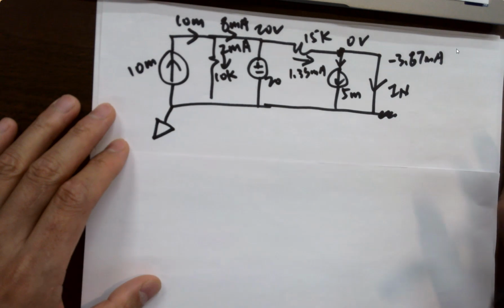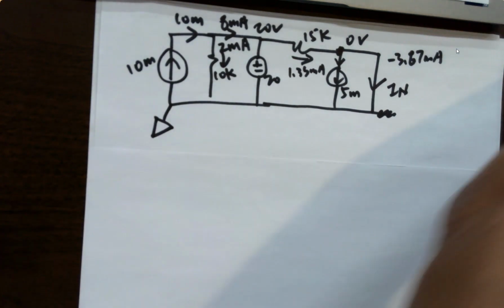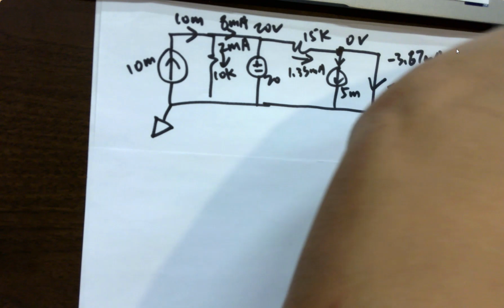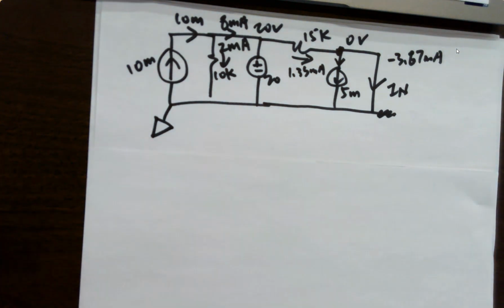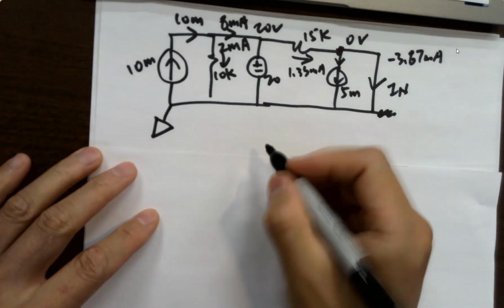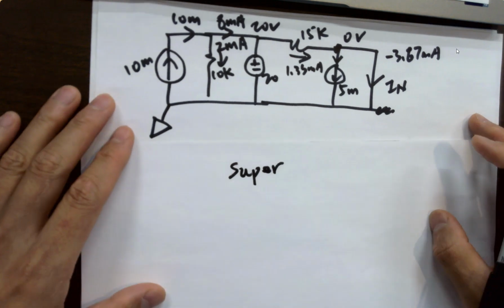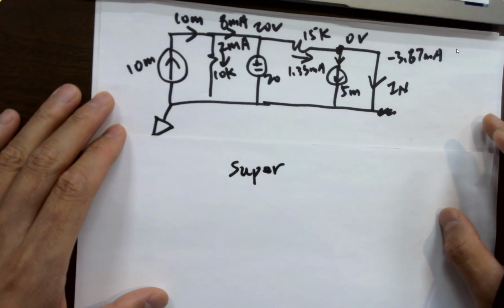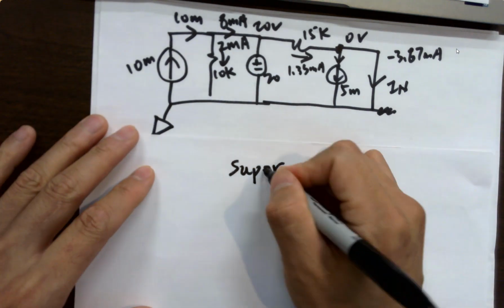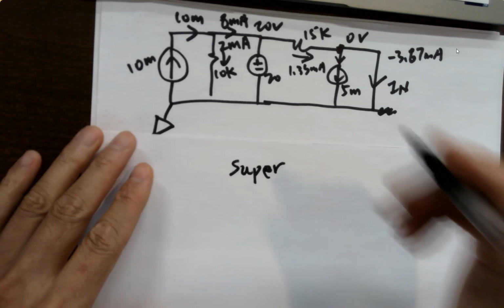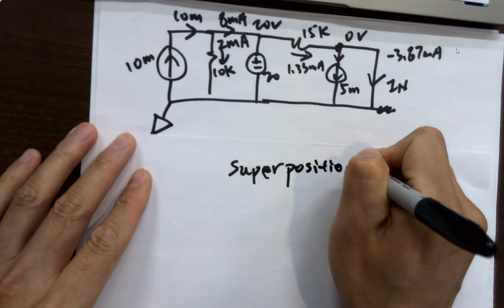But another way that I can verify, this is something I have to introduce because this is the very last problem in homework 5. And I'm telling students, this is my favorite method in circuit analysis. And a lot of people just ignore it. Why is it important? Because in the future, you are dealing with op-amps and other circuits, you will always be using superposition. I rarely use Thevenins and Nortons in real life, but superposition, always. Even when you get into graduate level circuit classes, you always think about the circuits from the superposition angle, you can always get things right. Important.